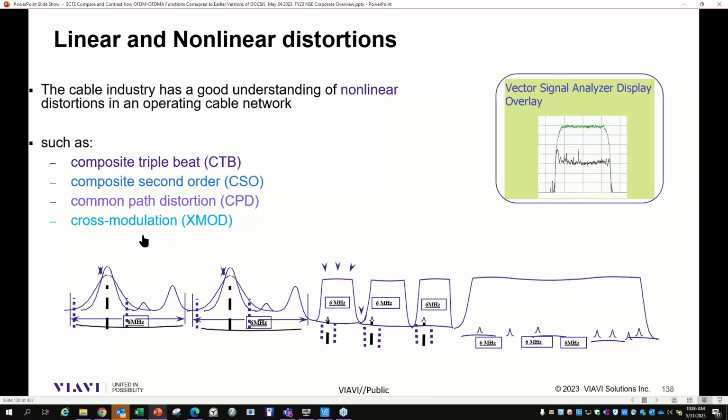The other one is cross modulation. What is cross mod? If you've ever gone to somebody's house and they're still using, for example, dial-up, and they're making a phone call, maybe you might have heard somebody else's voice, and you're hearing two voices, yourself plus someone else's. In the telco world, we call that cross modulation, or crosstalk. In the RF world, we call this cross modulation.